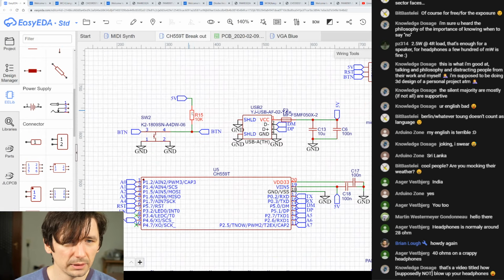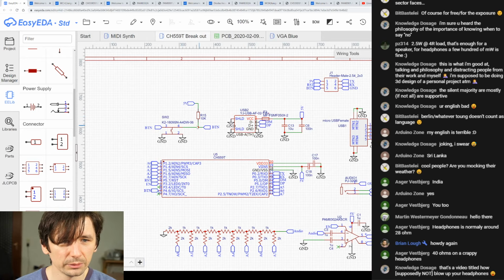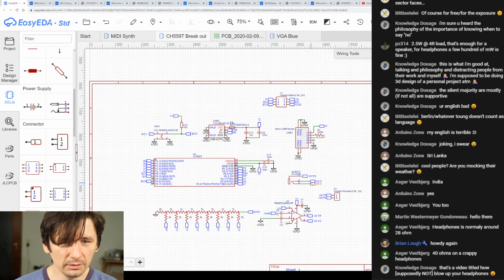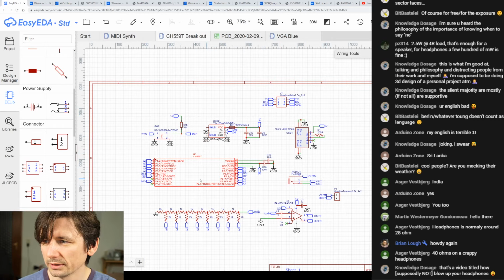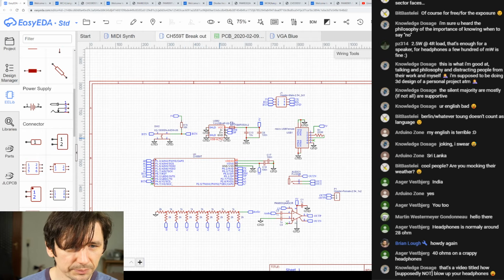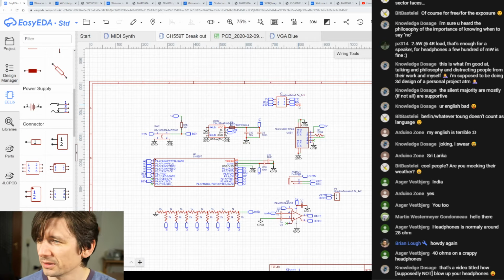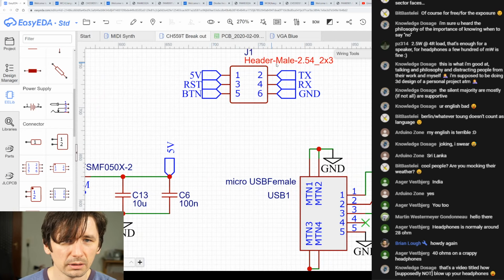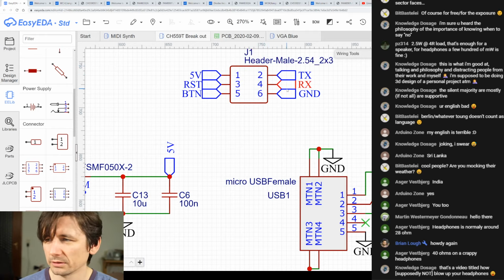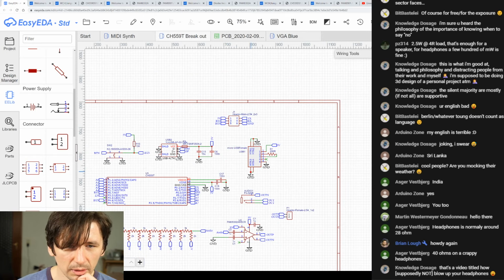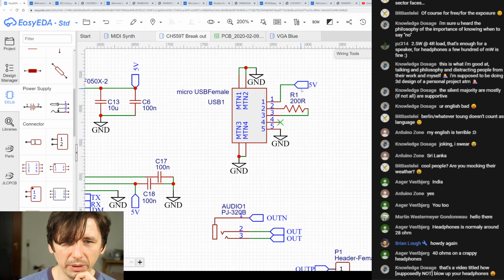Okay, so I took some time before today to convert this complete stuff. Maybe I will explain a bit. This is the button to be able to program the IC. This is the host IC. This is the USB-A female jack. Then we have this simple male 2-row, 3 pins a row connector to be able to program and test the board. And then we have the power.